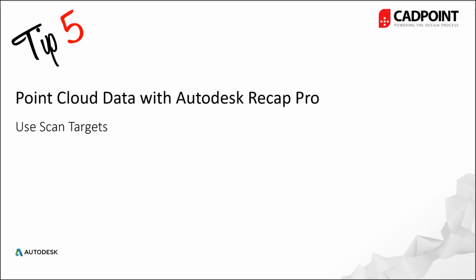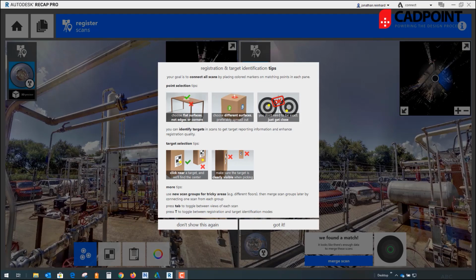If we need to select manual registration for whatever reason, as it does happen that not every scan can be auto registered, as it can't find common points across all of the surveying stations, you can manually register elements. Using the targets within the project that were placed on the site, you're able to use certain tools within Recap to be able to pinpoint to those particular targets.